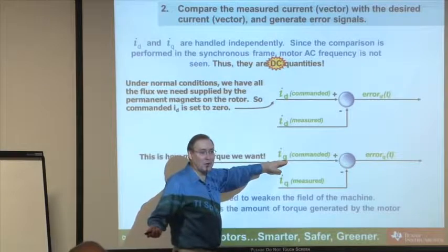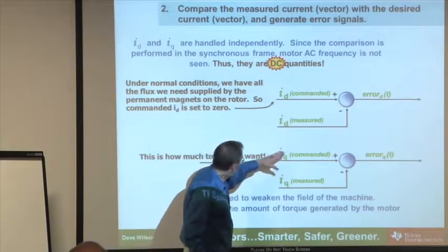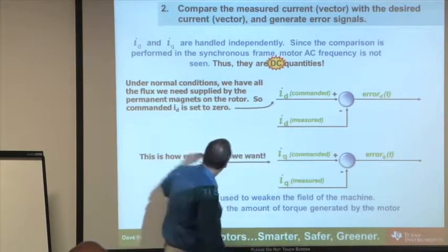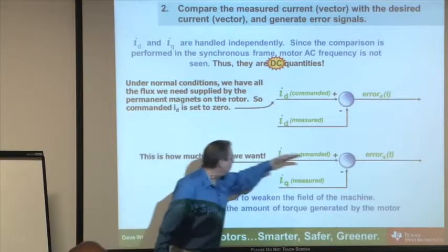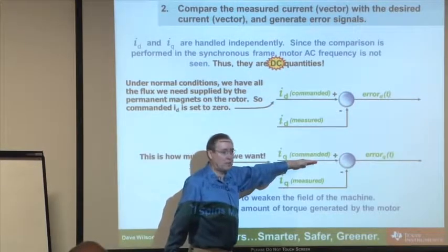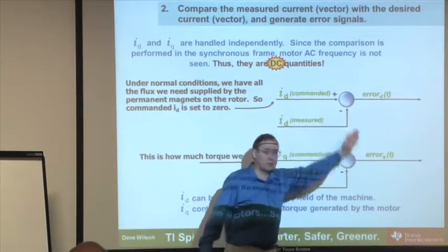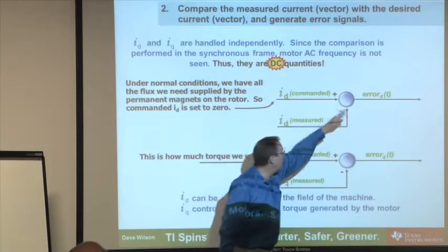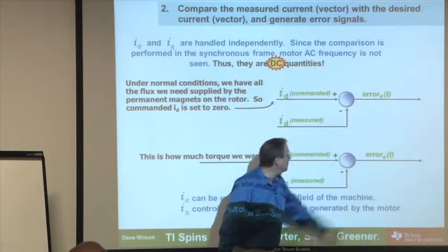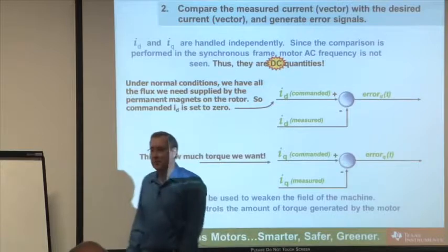That's torque. So now I have created a system where how much ever torque I want, I feed it directly into this current expression for commanded q-axis current, and I measure against that, and I generate the error signals for both axes. I've got 2 regulators now running on the synchronous reference frame, and finally, I finished with step number 2.